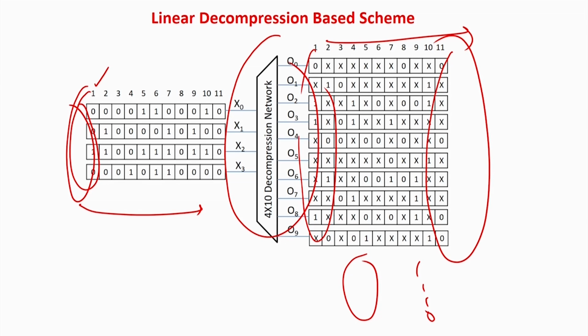So of course, as I told you, it's not a very simple problem, because it may be possible if I have maybe 1 x here and 1 1 here. Can the ATPG algorithm, the ATPG test pattern, be changed like that? Can I test some faults by keeping an x over here and a 1 over here? So then again it's a feedback to the ATPG algorithm.